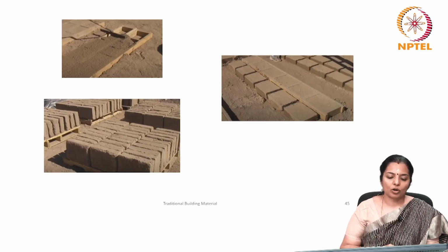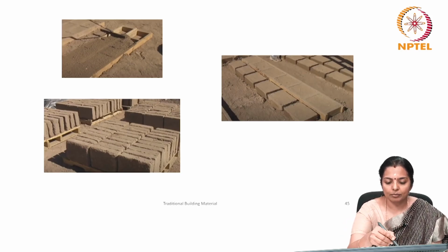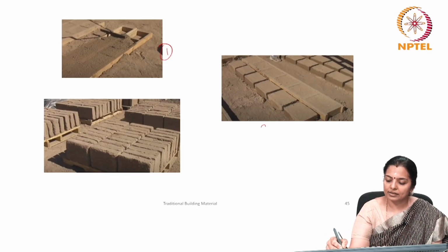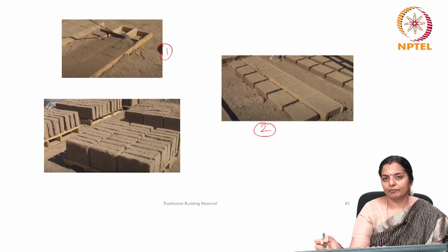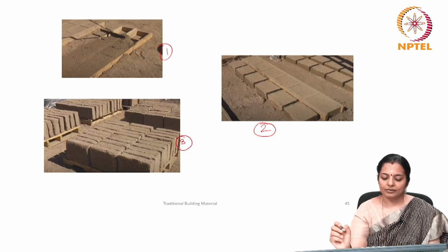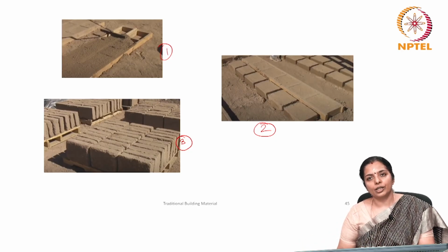So this is the process where the soil is placed on the blocks, and then it is left to dry under the sun, which is a renewable energy source, and then you stack the bricks in a particular way by sprinkling water on it periodically to ensure that it is not completely dry.